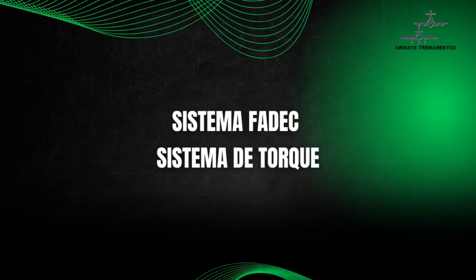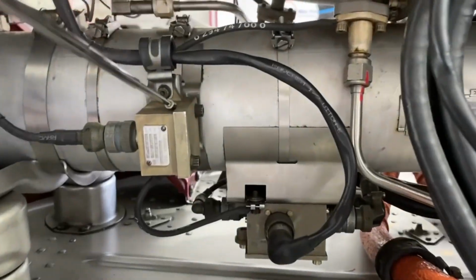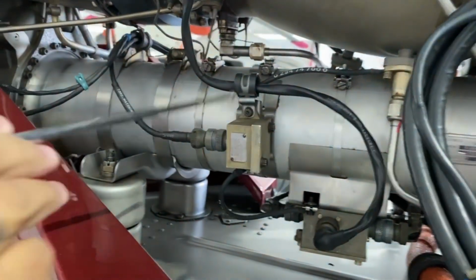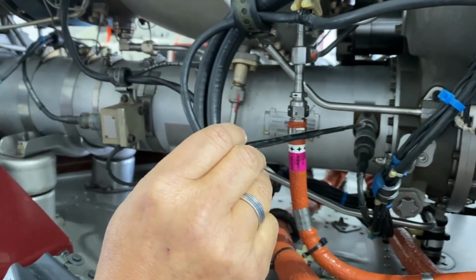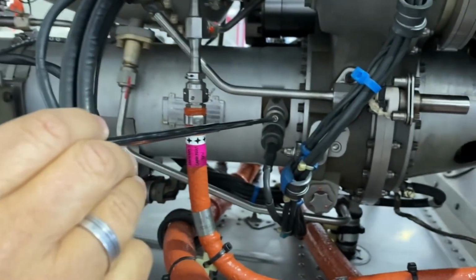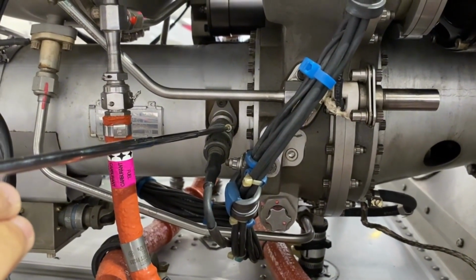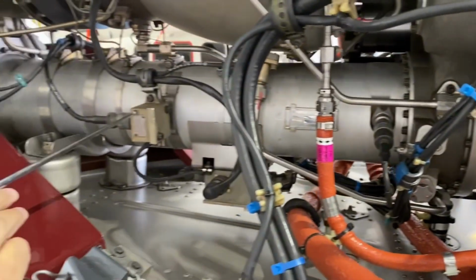Another vital piece of information that is also received by the FADEC is the data from the torque system. This specific engine features a specialized torque transmitter located right here. It actually measures the physical twisting of the internal shaft in real time. And this torque system includes a dedicated compliance box, a plate, which we will later learn much more about when we discuss what this compliance box is used for.